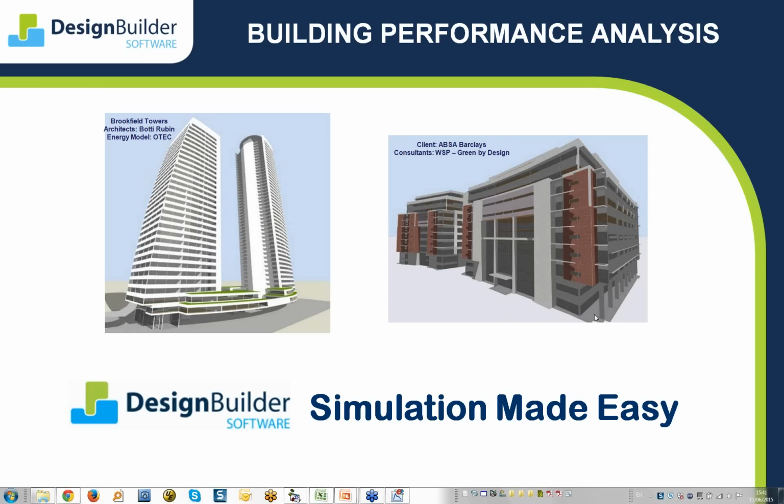There's a question asking whether the moisture transfer algorithm significantly increases processing time. I haven't done any tests on this, but because it uses a finite difference approach to the calculations, it's almost certain to increase the simulation time, and the time that it takes will depend on the time step. If you use very short time steps, then of course the simulation time will be a lot longer. So yes, it will significantly increase processing time.